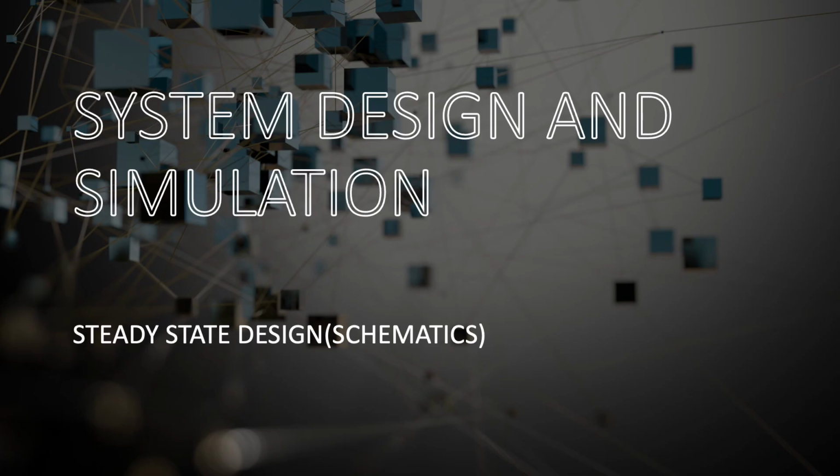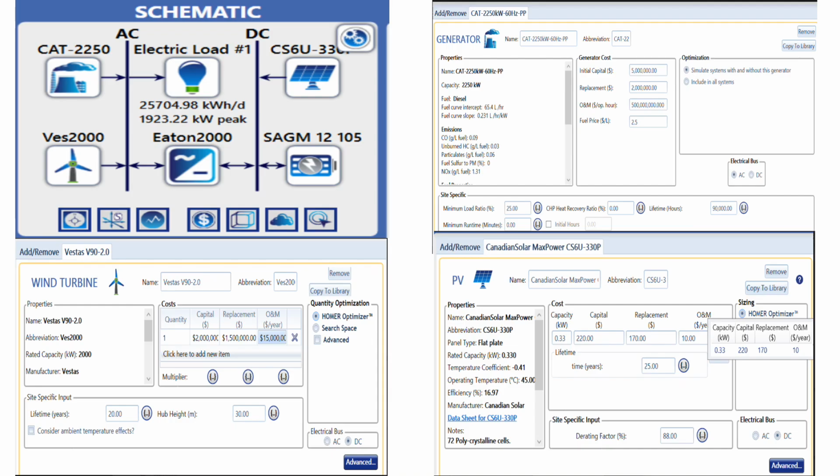Now we'll be looking at the system design and its simulations. The proposed hybrid system is developed on HOMER Pro and consists of a PV panel, a wind turbine, a battery, an inverter, and our electric load. The wind turbine is a 2 MW Vestas wind turbine that uses a doubly fed generator that can individually adapt to a 4-pole 50 Hz and a 6-pole 60 Hz. The capital cost of this wind turbine is $2 million. The replacement cost is $1.5 million. The operation and maintenance is $150,000 per year.